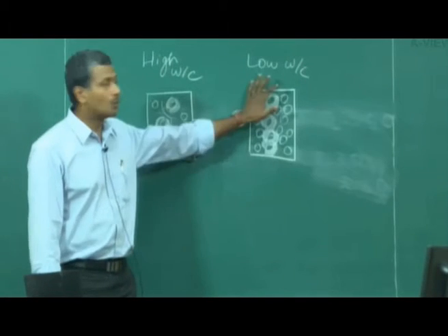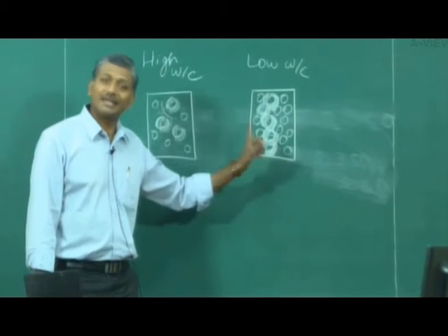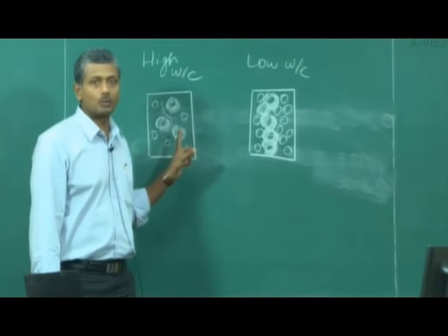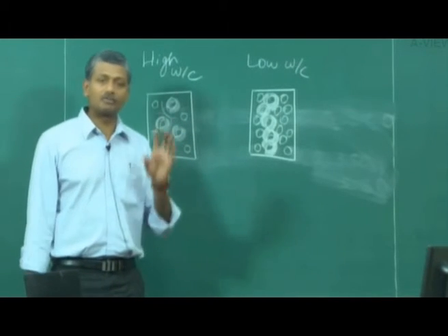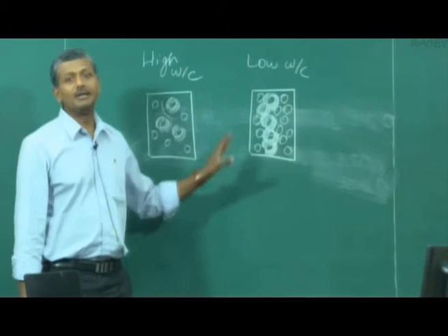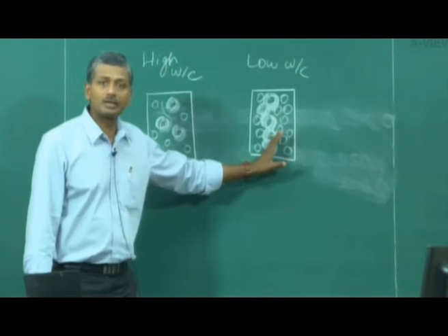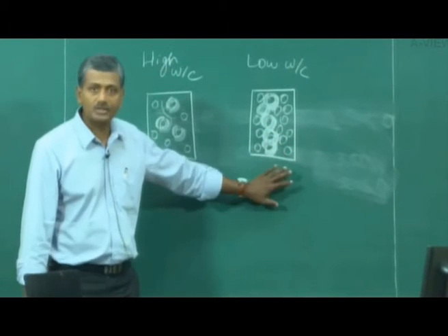Okay, so low water to cement ratio produces stronger and durable concrete, even though the cement does not hydrate as much as in the high water cement ratio system. Okay, now that may be contradictory to you, but if you think about it very carefully, that's what it will end up doing. So less porosity, less pore connectivity, much better strength and durability for low water cement ratio.